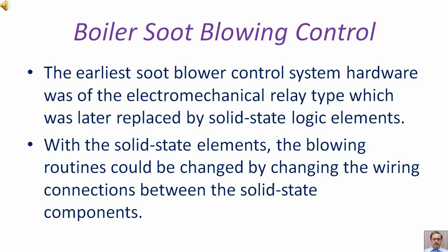The earliest soot blower control system hardware was of the electromechanical relay type, which was later replaced by solid-state logic elements. With the solid-state elements, the blowing routines could be changed by changing the wiring connections between the solid-state components.